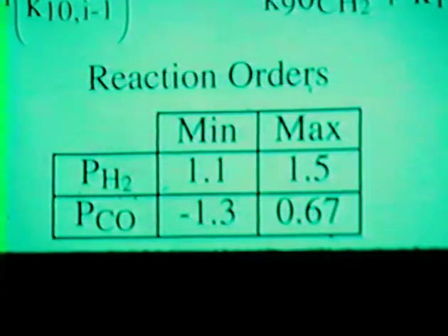At this high pressure in this study, I've just shown that the hydrogen order was 1.2 as determined by the power law expression, and the CO was a negative 0.2. Some earlier work that we did on a similar catalyst at 1 atmosphere pressure and at concentrations of hydrogen and CO half of what were used in this study, we observed a hydrogen order of 1.4 and a positive 0.6 order on the CO. So in both cases, this model will allow for those different cases.